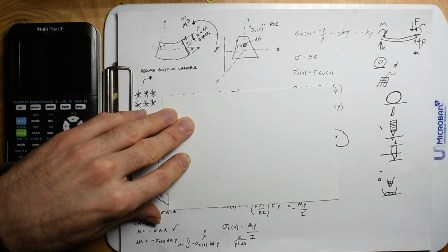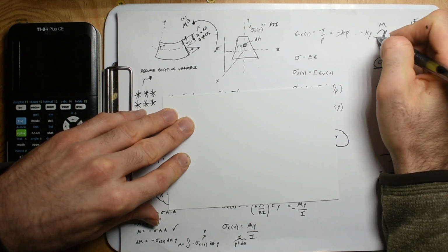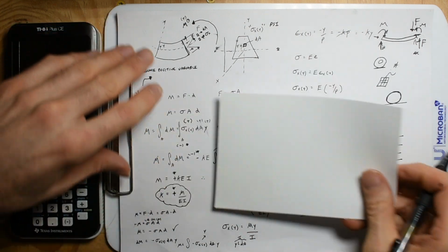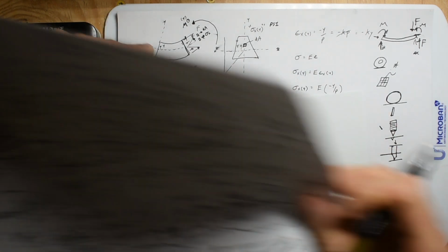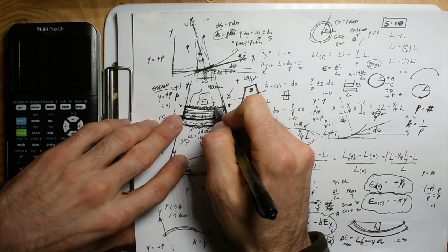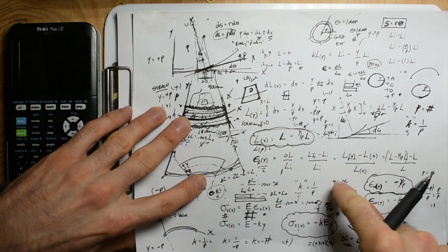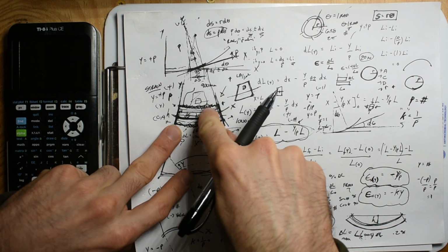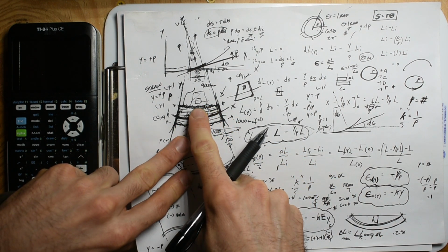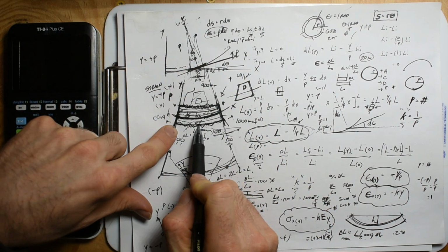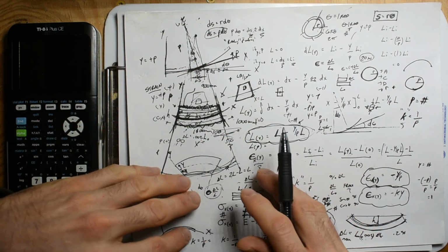When we do that, it's fascinating that we don't get any axial loads, but we do get internal loads based on what we talked about. Just from geometry, this gets crunched, we see a change in length, so going the direction of strain, we see that change in length. That change in length must indicate compression. This change in length down here must indicate tension.